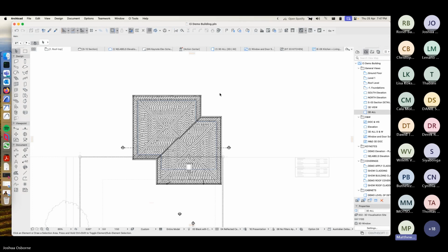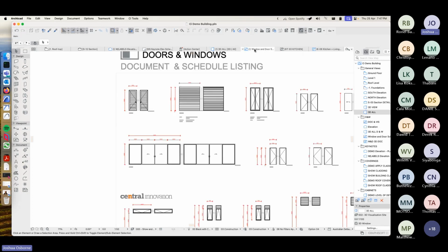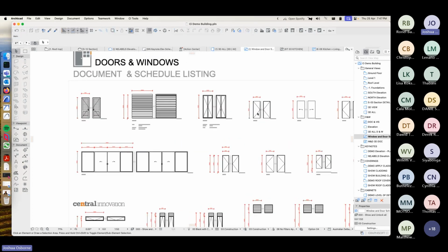So that was relating to the door and window tool. To the door and window schedule? No, you can't. They are entirely just the elevation views in this schedule. That's interesting. I've never had anybody ask that before. But no, you can't do that. So if you did want to have the plan views like you do in the interactive scheduler, you probably will need to stick with that one. Yeah, it's strictly elevations only.